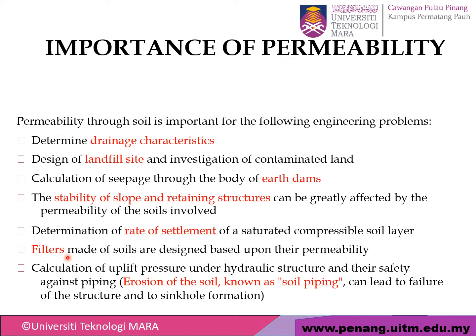Filters made of soil are designed based upon their permeability. And the last one, calculation of uplift pressure under hydraulic structures and their safety against piping. Piping is the erosion of the soil, known as soil piping, which can lead to failure of the structure and to sinkhole formation.